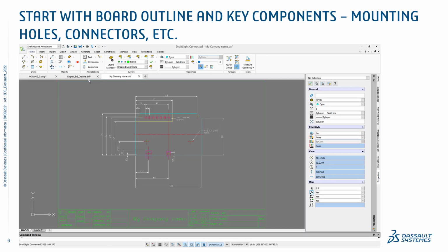The reason is that PC board layout does not just start from a blank page or an arbitrary board outline, mounting holes, and connectors. A mechanical engineer somewhere started the board outline, how big it is, and where the mounting holes and connectors that interface to the outside should be. Why should we, as PCB designers, not be able to use this information? And that's where DraftSight and DXF come into play.